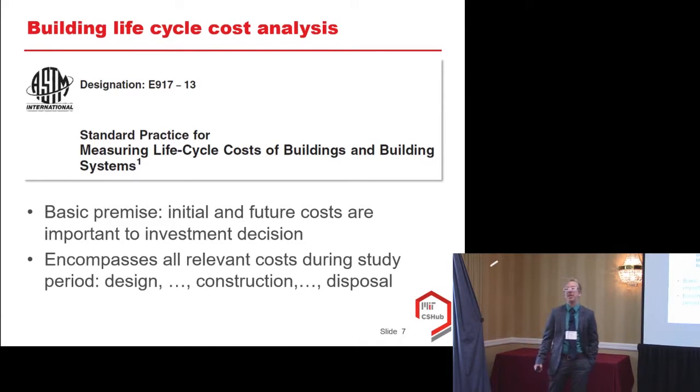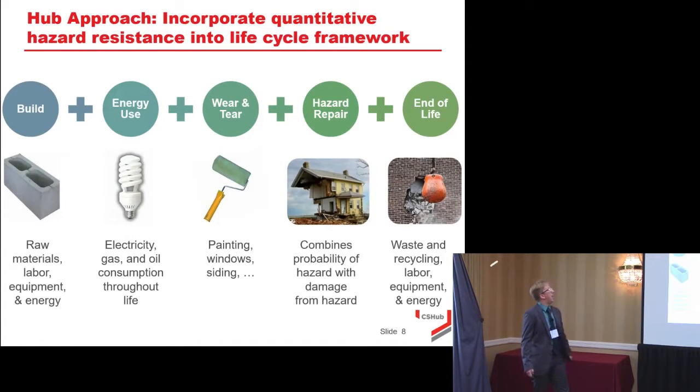Fortunately, on the building life cycle cost analysis, we don't have to start from scratch. There's an ASTM standard that helps walk you through it and make sure that you're incorporating all of those initial and future costs. It's really rather thorough, and a pretty accessible document. It starts all the way from design right through the disposal of the building, so I recommend getting familiar with that guide. I'm going to show an abbreviated approach here. We're going to be comparing two different buildings in an apples-to-apples way, so I haven't included the design phase, assuming that'll be pretty similar here. And the scope of our study isn't going to extend all the way to the end of life, so we're going to focus on these first four.